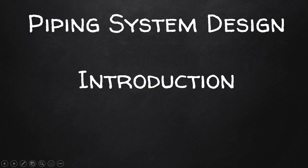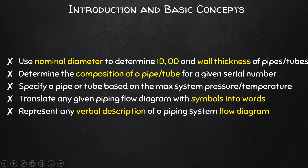In this lecture we will cover the basics of piping, from the concept of nominal diameters, wall thicknesses, etc., so that you will be able to determine the internal and external diameters of pipes and tubes. We will also have a look at various pipe classifications based on concepts like serial numbers and piping schedules, and also consider physical limitations of piping, such as pressure and temperature.